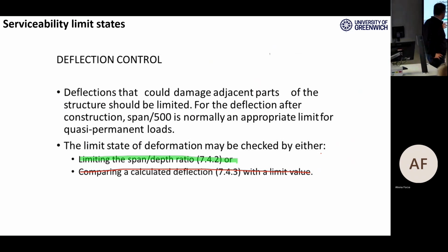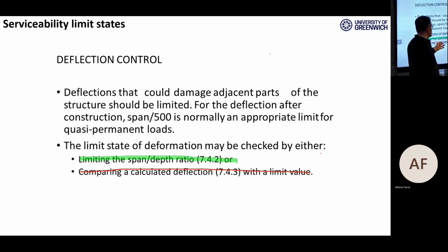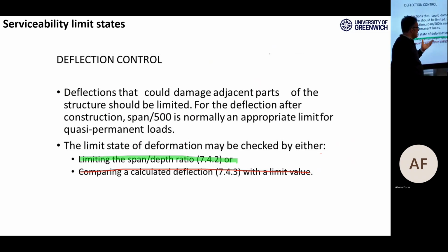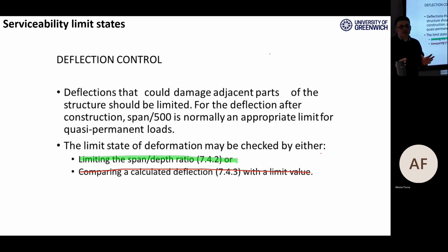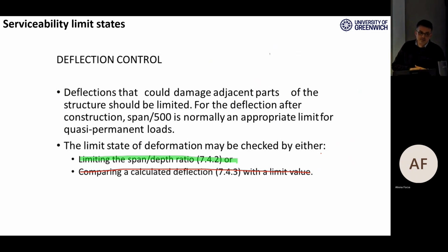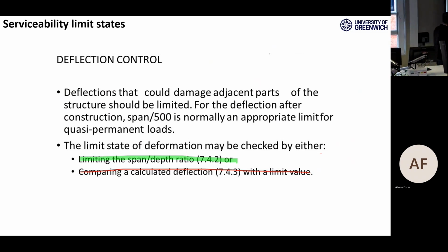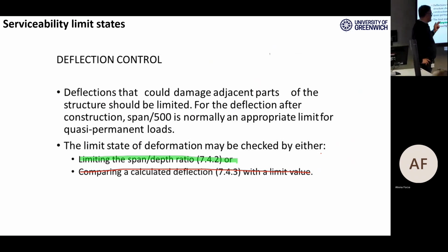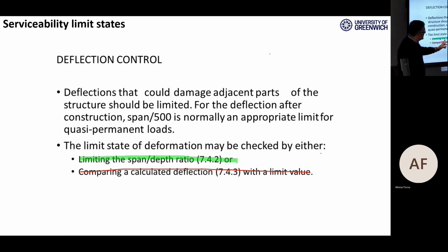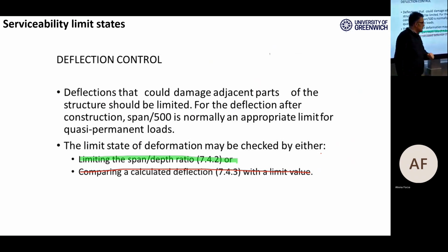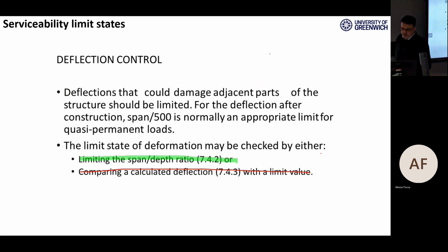The more complex is comparing the calculated deflection with the limit values, which means that you go and calculate deflection based on the structural analysis in ETABS you're doing, or going for a simple approach by limiting the span to depth ratio according to section 7.4.2, Eurocode 2.